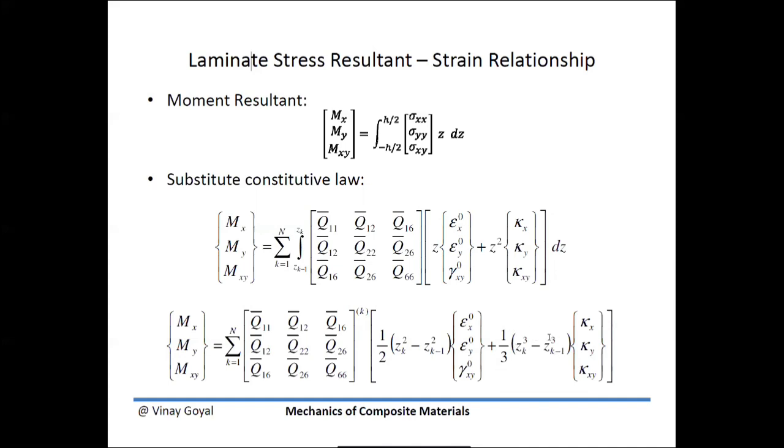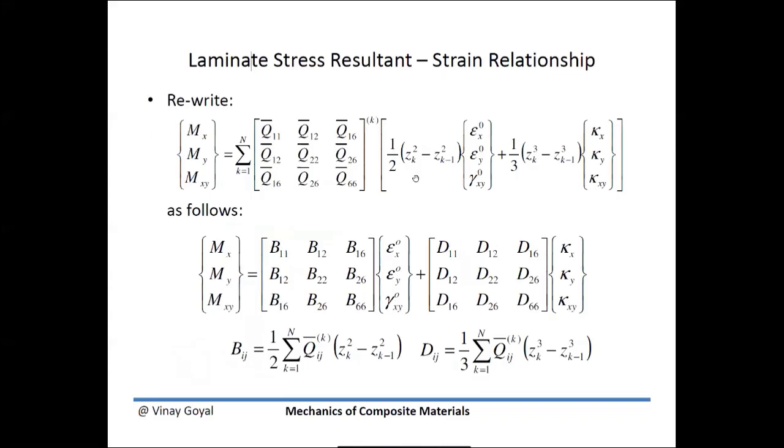And so, again, this is fully known for a ply. The location of the ply is known, so you can calculate that coefficient. And so you can readily calculate these coefficients. For simplification purposes, you quickly see that this times this we already calculated before, so this is exactly the same coefficient. And this multiplication here times the 1/3 is new, and that's your bending stiffness.